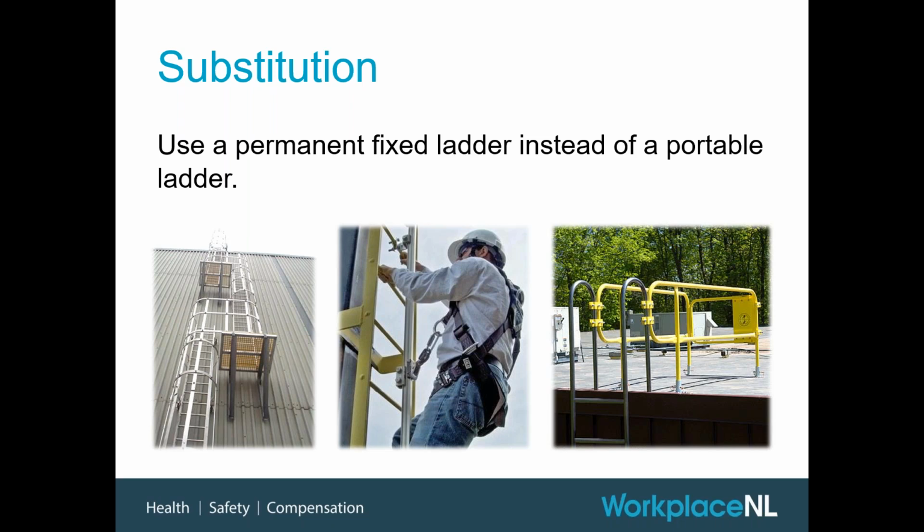And on the far right hand side, I've just got a picture of a fixed ladder that leads up to a flat roof, and it's got this really nice little guardrail that comes off the ladder and goes in that 6 feet that I mentioned earlier, which is important for the roofing legislation. That allows workers to get up on the roof and then have a safe path to access that inner area, inside that 6 foot from the edge realm, where they don't necessarily need to have any kind of PPE on, so there's no need for fall arrest or fall restraint, which we're going to talk about later.